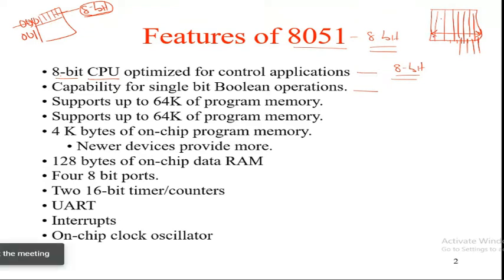But even though the memory location has 8-bit data, in the microcontroller we can also handle the individual bits. Suppose you have the data 100 only; in the processor you have to represent the remaining bits as all zeros and consider the entire 8-bit data. But in the controller, whatever specified data we have, suppose 100, we can handle only that limited number of bits. So bit accessibility is there. Individual bits can also be handled in the microcontroller system.